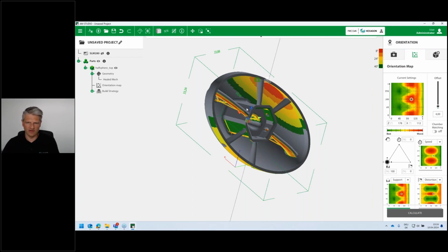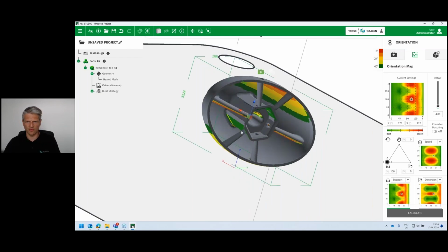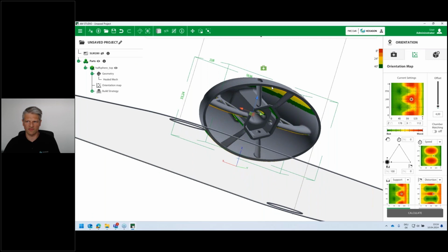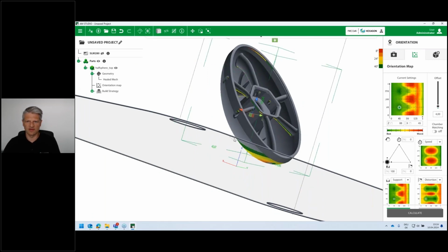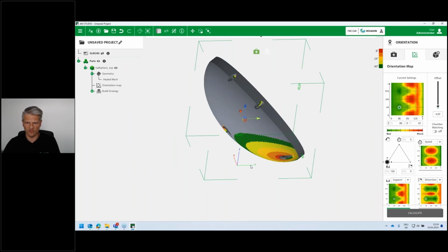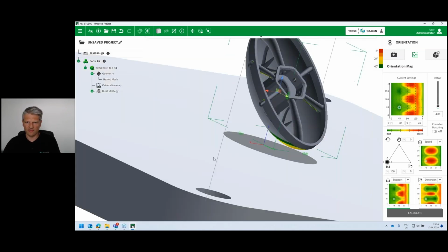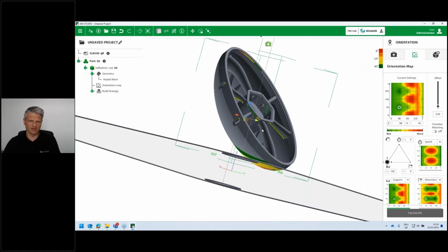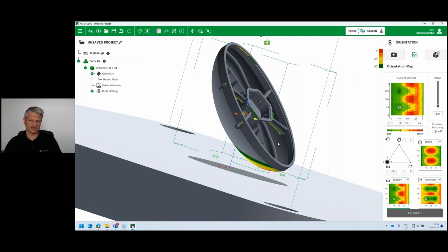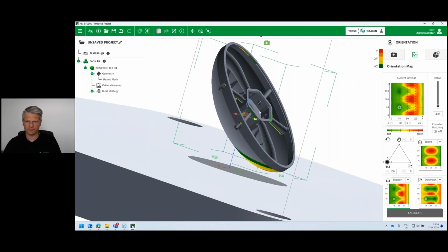There are a bunch of those surfaces, and they also have a certain height from the base plate. In comparison to that, in a green orientation we only have to support this bigger area on the bottom and some smaller features in the inner part. I think it's pretty intuitive that this is a better orientation than the ones before.